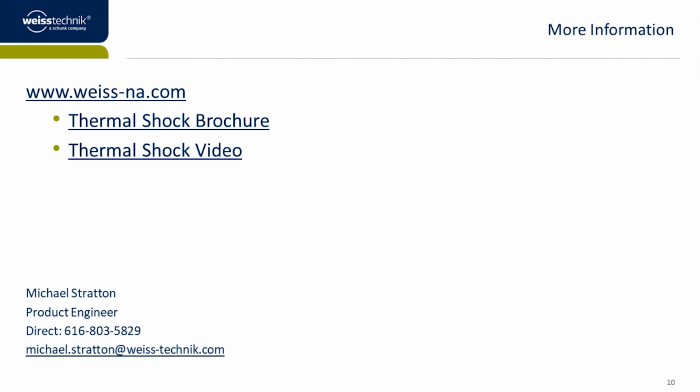Okay, great. Another one came through here via email: what do you do differently if lithium-ion batteries are the test sample? So something to do with battery testing. Another great question. Yes. For lithium-ion battery testing, the same safeties that you would see in a standard temperature cycling chamber would also go in the thermal shock chamber, but the difference is we would have two sets, one for the cold zone and one for the hot zone. That way, regardless of the basket position, your product will be accurately monitored and safety will be properly accounted for.